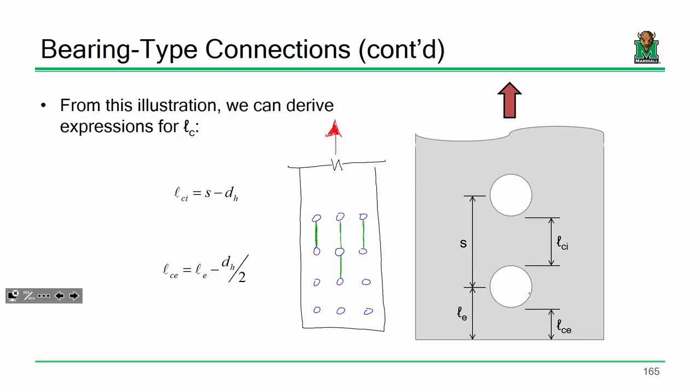What about when you have a staggered connection? That's a good question. The answer is you just have to be a little clearer on your bookkeeping. So I'll do a simple one just to kind of explain. If I had a staggered connection and it was somewhat complicated, I'd probably just make sure I was taking each bolt one at a time and getting the right LC for each one.